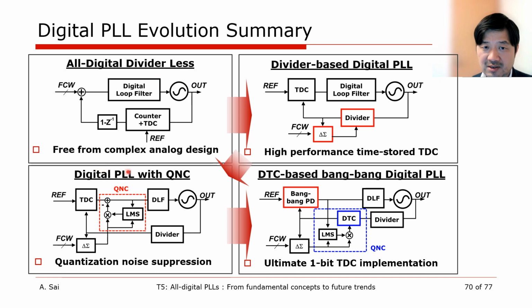However, researchers were not satisfied with the quantization noise of TDC, so they improved it by introducing the divider, slowing down the TDC input speed, so that high performance TDC, such as time-stored TDC, can be utilized for suppression of quantization noise and the nonlinearity of the TDC.